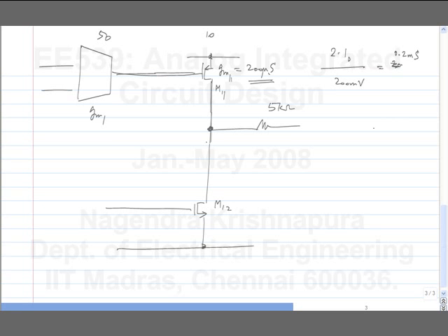What's ID? 20 microamps. Yeah. So this is a small current, but like I said, right now this is just a quiescent GM of M11. You need at least this much, but to drive a signal into this, you need a large quiescent current.